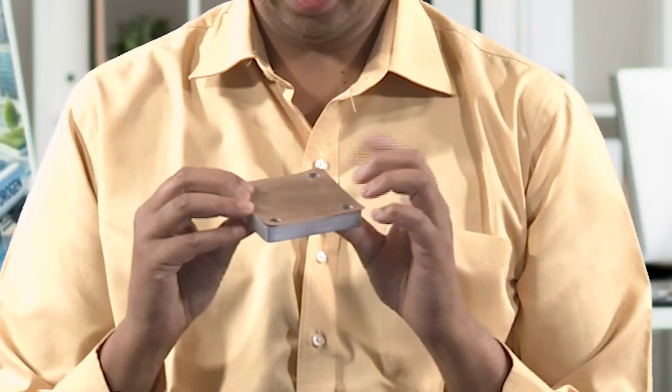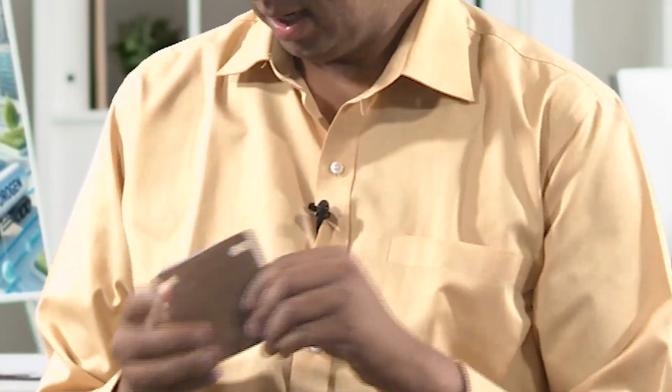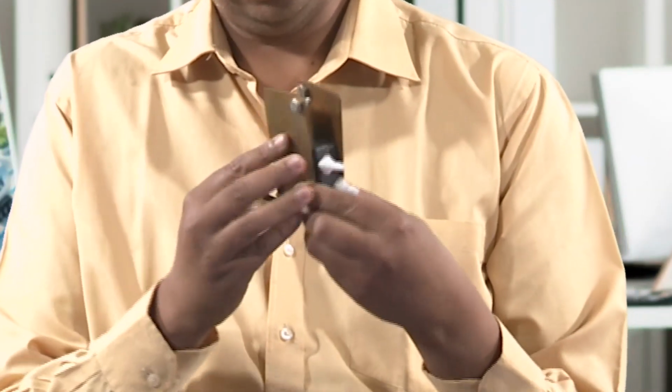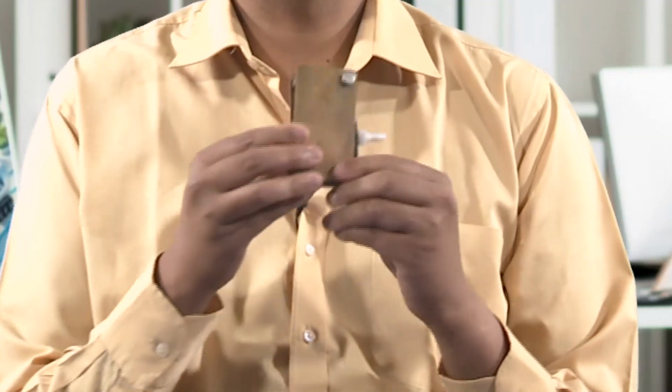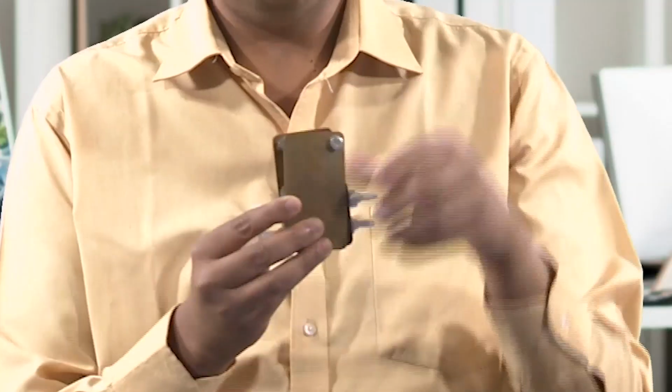The electrolyzer also looks very similar most of the time. The only change that we can expect between a fuel cell and an electrolyzer is the catalyst and the gas diffusion layer. This is the end plate, and this is the gasket, which is basically used to isolate these end plates from the electrical circuit. And then we have the copper plates, as I mentioned. These are the current collectors, and this is how they are placed together, and we have the electrical connections at the center, between these two plates.